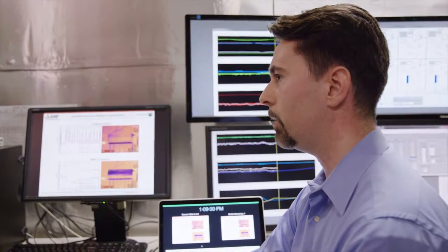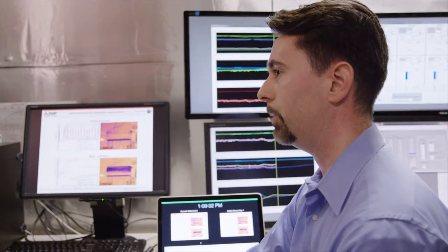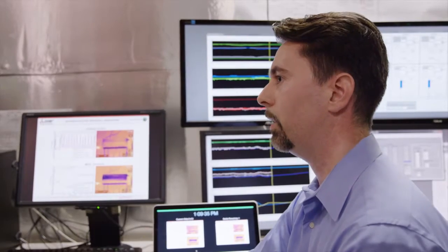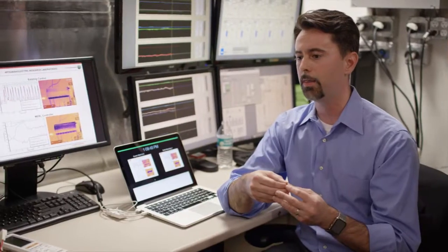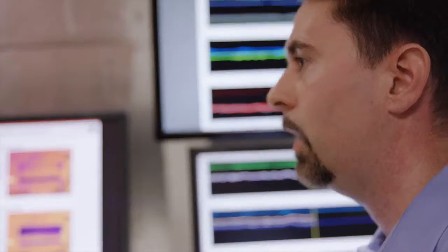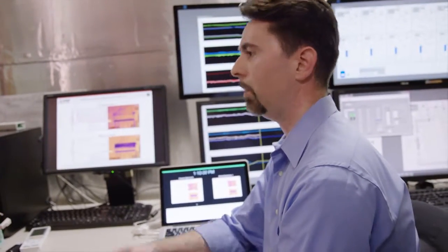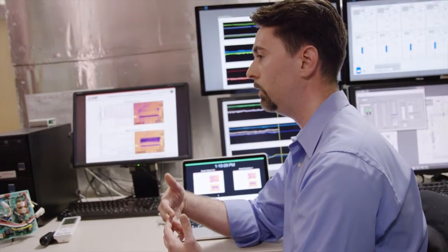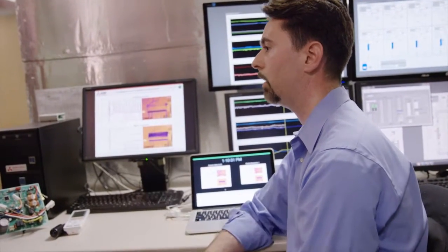We use simple models of the air conditioner calibrated from this laboratory to predict the future response of these air conditioners and make decisions at the current time that are predicted to be optimal in the future. And by doing so, we can enforce constraints and improve energy efficiency. The control algorithm uses a model to predict the future response of the air conditioner and solves an optimization problem online to compute actuator commands that are predicted to be optimal. The optimization problem is solved iteratively,